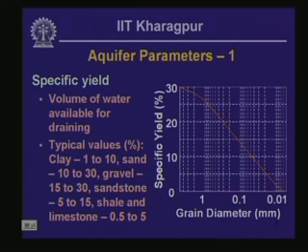So it is equal to the total amount of moisture that is present in the underground formation minus the amount of moisture that is held within non-interconnected pore space, as well as that which cannot be tapped because of excessive capillary tension, plus those amount of water which are absorbed on the surface and tightly held, in fact, on the surfaces of individual grains that make the formation.